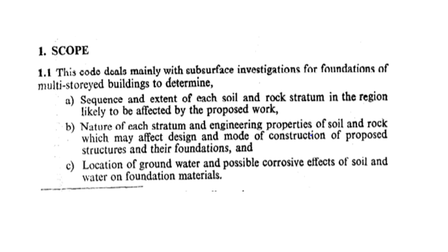So basically, what you want to determine is the nature of the subsoil profile, and you also need to determine the engineering properties of the soil, because you need to assess the suitability of that particular site soil as a foundation material. And then lastly and most importantly, it is your groundwater table which is going to decide many of the consequences on your structure, so that is very important.